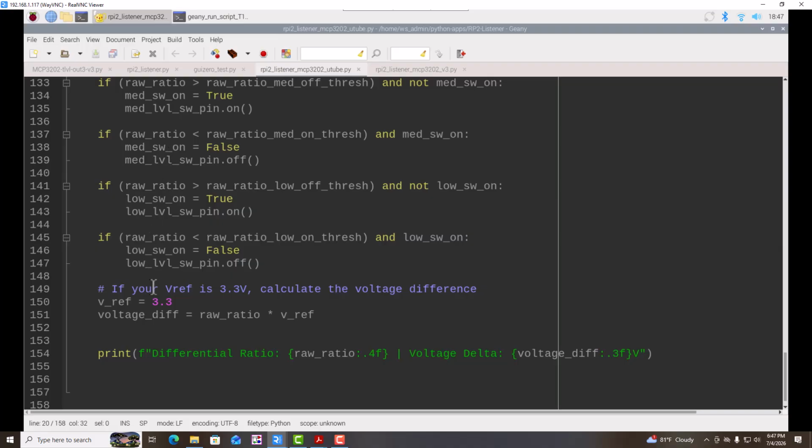And finally down here, this is going to print on the screen of the terminal at the Raspberry Pi. See, I'm using a VREF of 3.3 because the Raspberry Pi logic and the bias on the ADC is 3.3, so that's what we use for the reference.